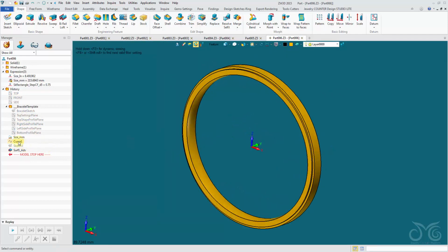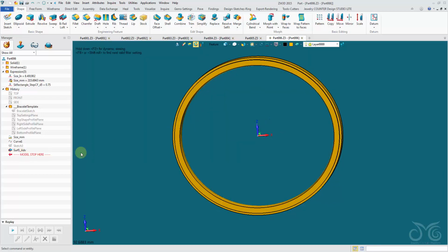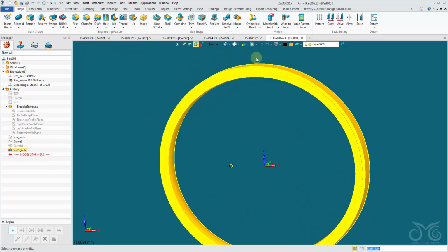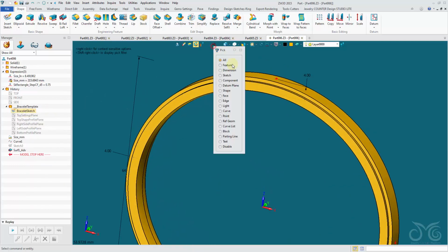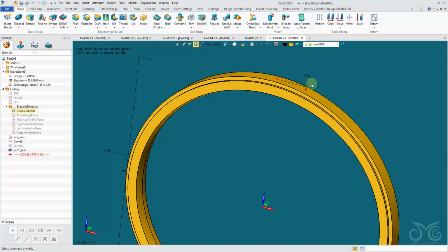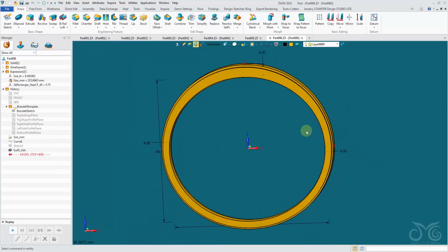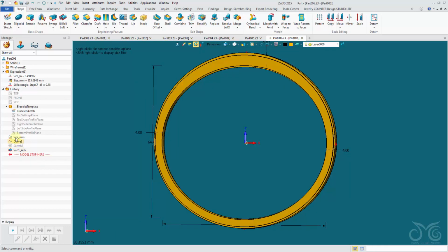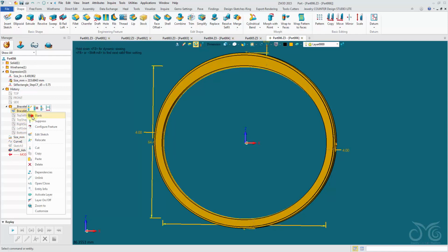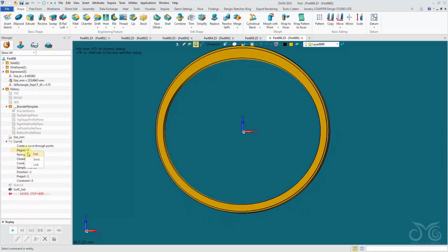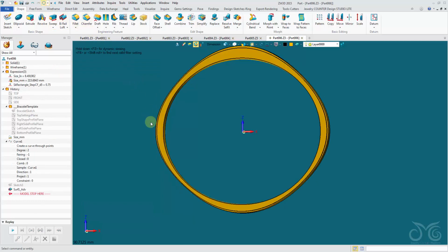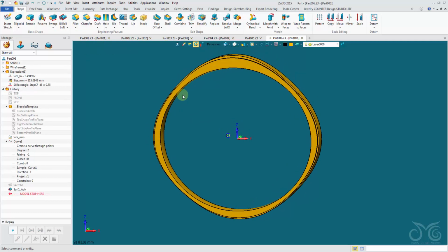We can play around with the outer curve to make modifications to the shape of our shank. We can also play around with the datums, the offsets that we have there. For example here, we see it update. Let me just blank this out again. Open this up, we could change the degree here. Drop it down to 2. Regenerate. You can see the effect that it has.